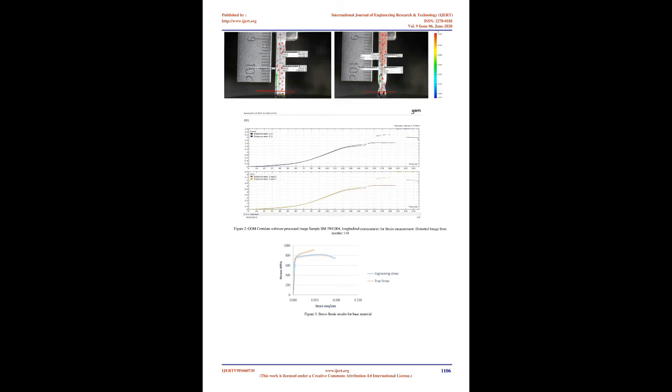3. Analytical results. Stress-strain curves. Stress-strain curves for all 3 welded connection elements, base metal, filler material, and heat-affected zone, are produced. For the base material, a sample of S690Q steel is taken, whose dimensions are tabulated in Table 2. For the filler material, G46 material is used. This combination makes the studied joint undermatched in its welding properties. Also, a small specimen is taken from the center core of the heat-affected zone.